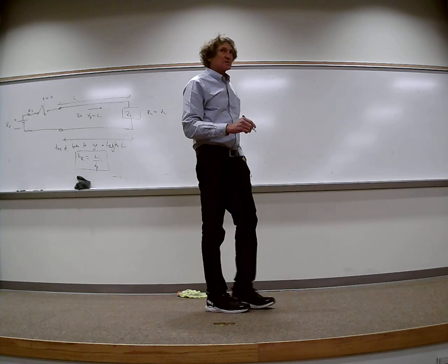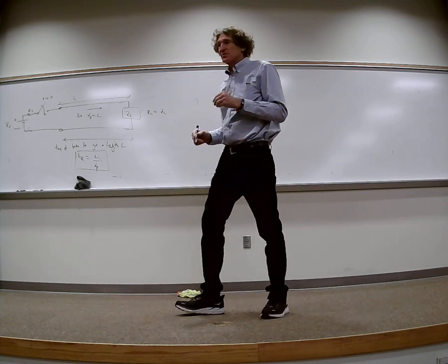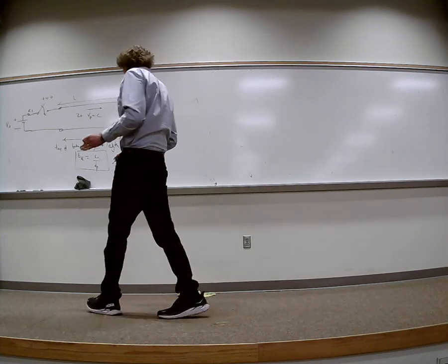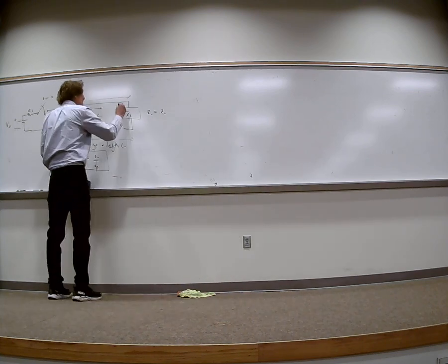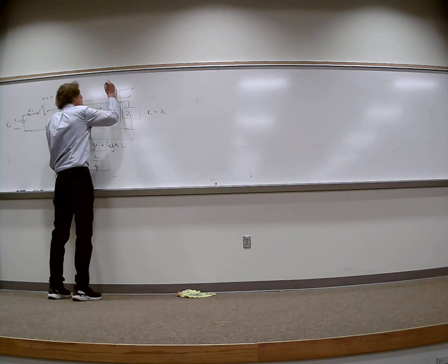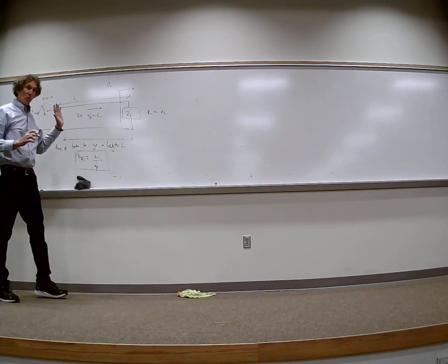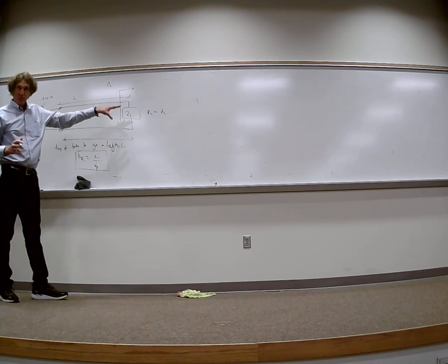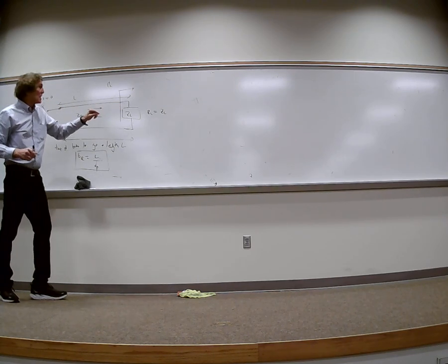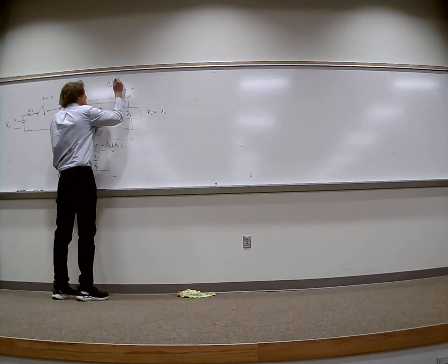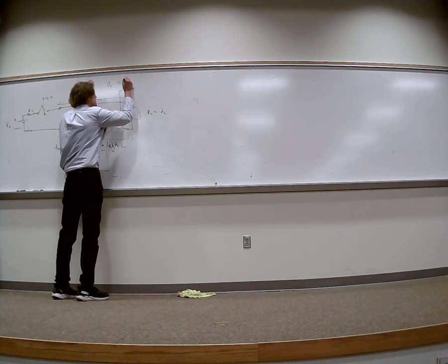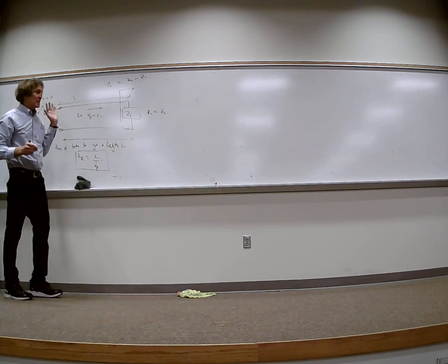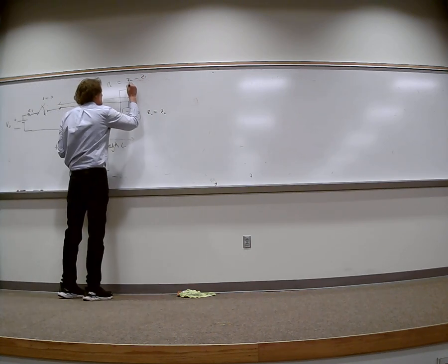Now the next thing we need is the reflection coefficient. Please follow me on this one. People will mess this up. Not this part, but the next part. Right here, we have a reflection coefficient of the load. Do y'all follow me? The wave comes in, it hits. Some is reflected, some is going to be dissipated or transmitted. So that reflection coefficient, just like before, is always the impedance you're going into minus the impedance you came from, which is the characteristic impedance of the line, divided by the sum.